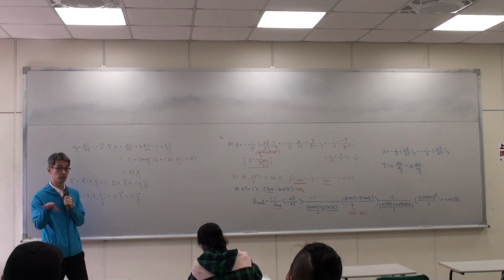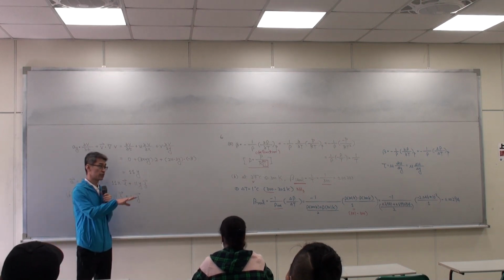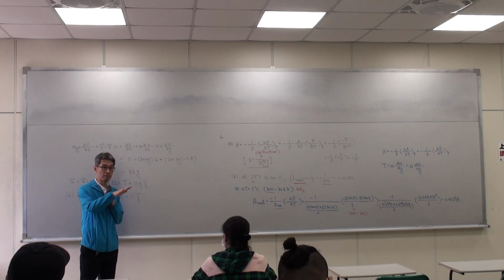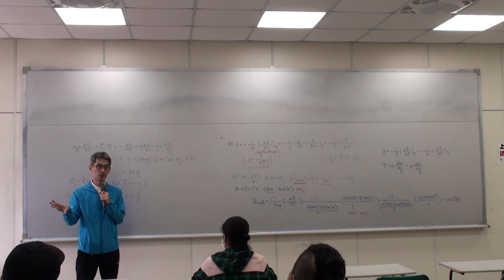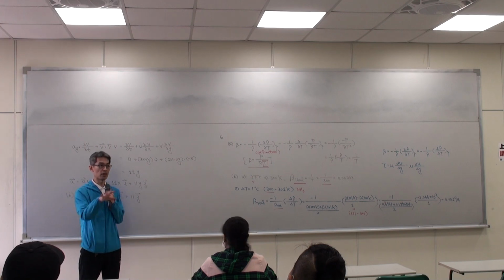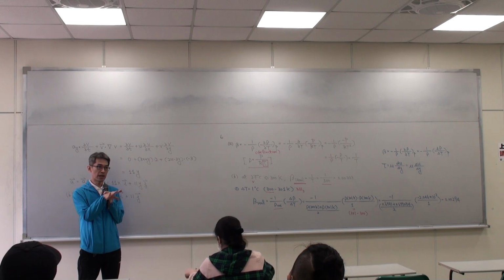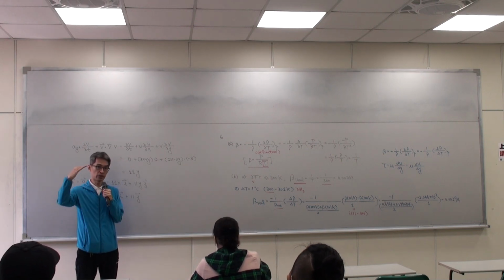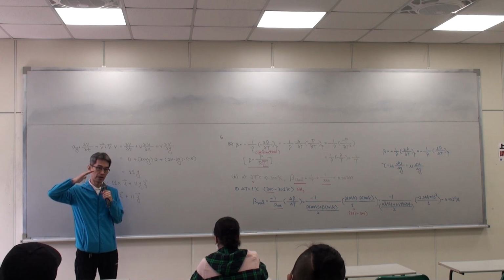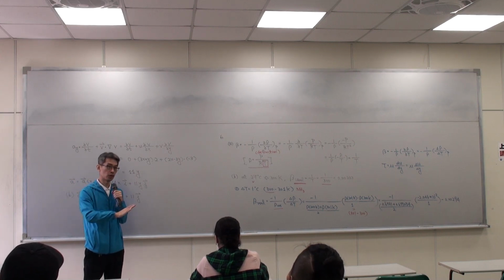So in this kind of free boundary condition, what kind of condition needs to be satisfied? Usually the pressure. For example, the sea surface, why do they maintain this kind of shape? Because on the surface they should have atmospheric pressure. If the pressure is less than the atmospheric pressure, the air would penetrate into the water.